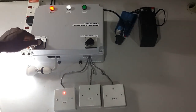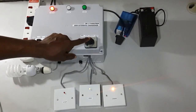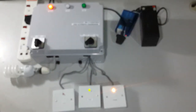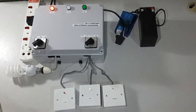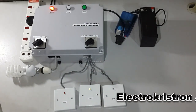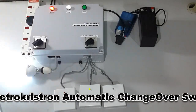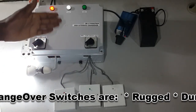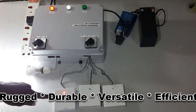But if you cut this off, then mains goes off, and then the AutoStart switch instructs your generator to start automatically. But as soon as power is restored, there is an initial delay to take care of transient or power surge, for those few seconds when power has just been restored. Now power has been supplied to the load, and then your gen has gone off.